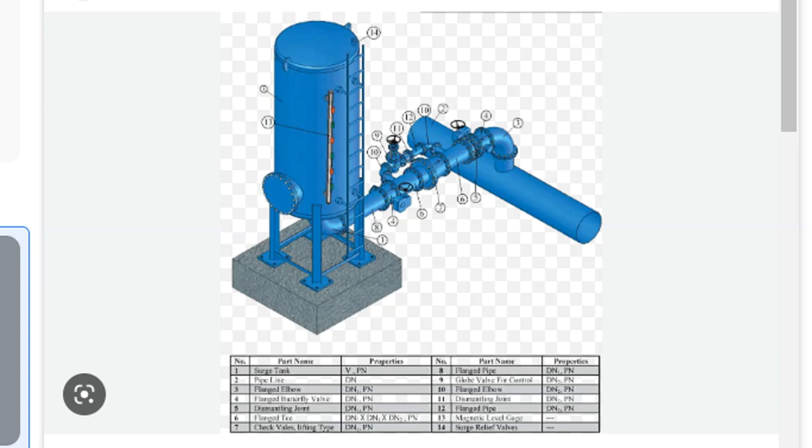This is actually that valve which I was talking about. You can see that this is that valve and this is a surge tank, and it's a device for storage of water and also used as a pressure neutralizer in a hydropower water conveyance system in order to dampen excess pressure variance, right?